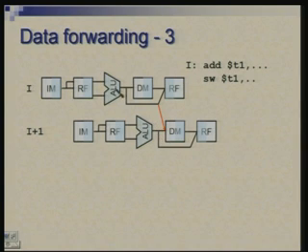So, whether it is add instruction, we can forward from the output of this stage. It is basically the output of ALU, which will be simply passed through this stage without any modification, will be available at the end of this stage, okay, and then passed on to the input of the data memory, right. And if it is a load instruction, which is the first instruction, then of course from the output of data memory you can pass on to the input of data memory.